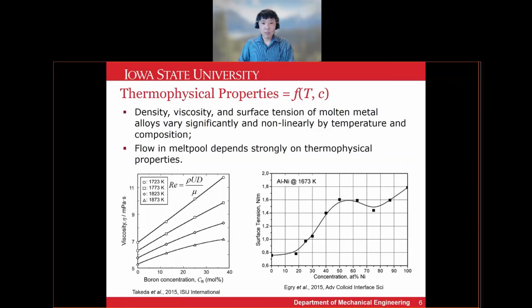The equation in the plot is for the Reynolds number, which shows the relative dominance between the inertia and the viscosity. If the Reynolds number is low, the flow is called laminar. You can imagine how honey flows as an extreme case. If the Reynolds number is high, the inertia term dominates and the flow is turbulent. You can imagine a fast and violent flow.